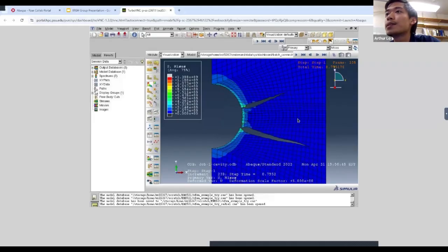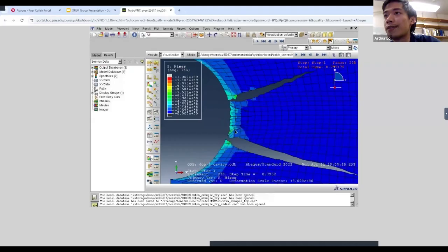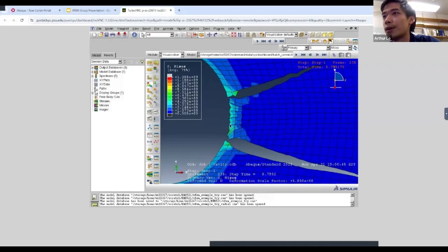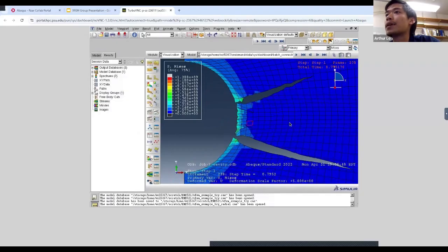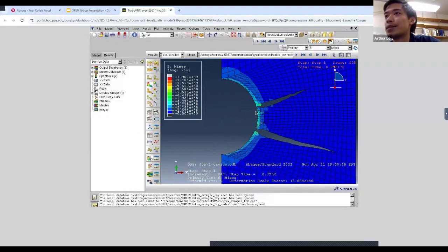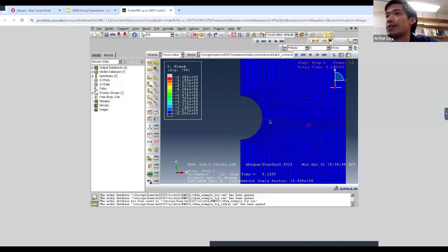But you can see that even in the middle, you have even these smaller cracks that are going within the elements. But eventually, the deformation localizes in these larger fractures. And these smaller fractures do not grow quite as quickly as those larger fractures.